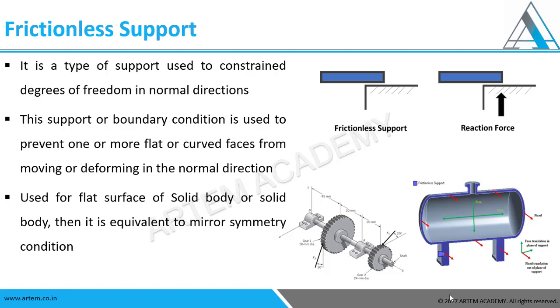According to the consideration of the model, this is nothing but a mirror symmetry or reflective symmetry condition, or many different kinds of symmetry regions. Wherever it is there, we can go for frictionless support. We discussed each and every support along with real scenarios so that you can observe the functionality, and according to the functionality, which support suits best.